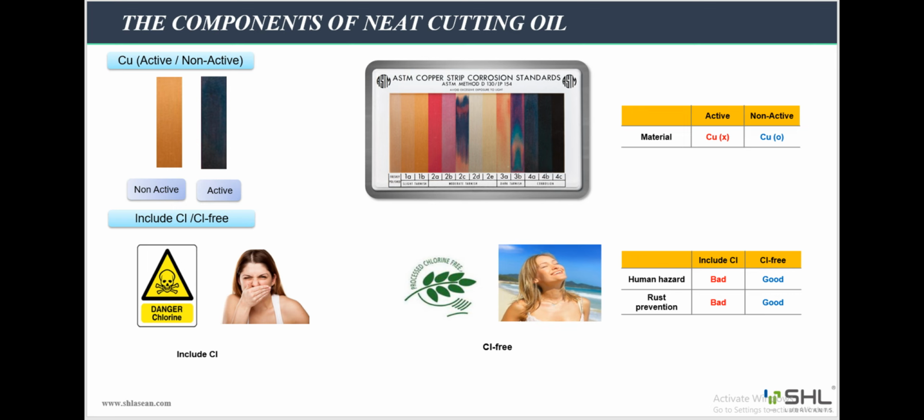With the chlorine additive, it has the advantage of extreme pressure and good detergency. However, chlorine additive is a toxic additive that seriously affects health, especially the respiratory system. As soon as mid-2017, the U.S. Environmental Protection Agency may outlaw most chlorine additives, leaving the metalworking industry searching for alternatives that won't sacrifice performance or tool protection.